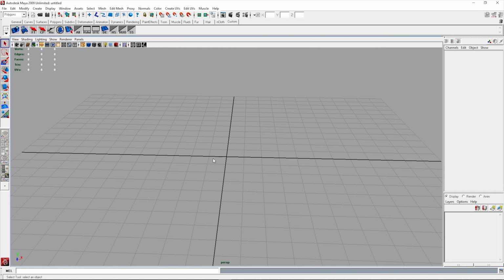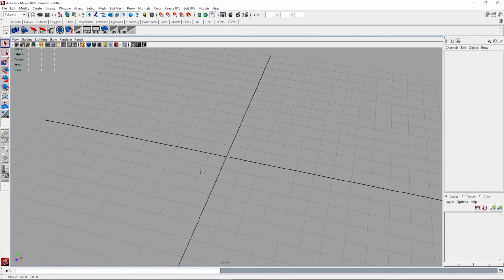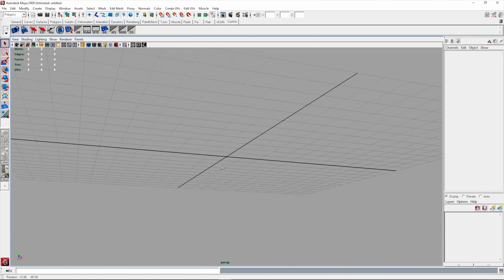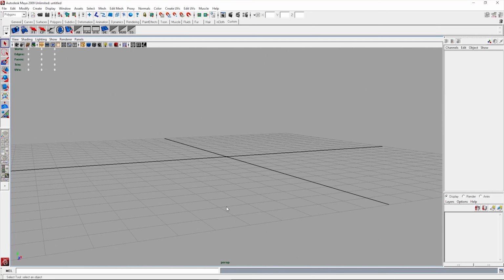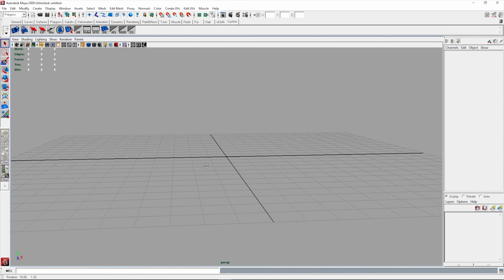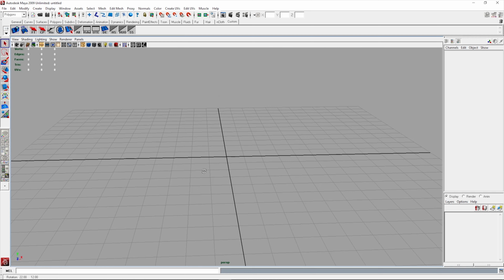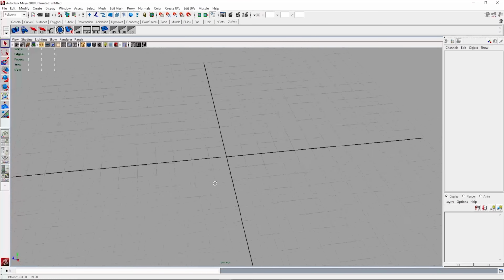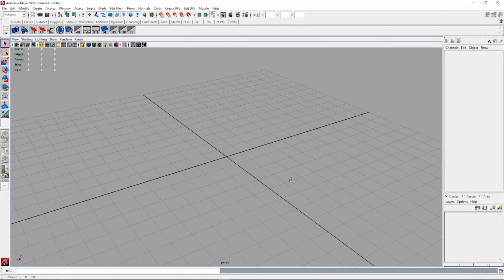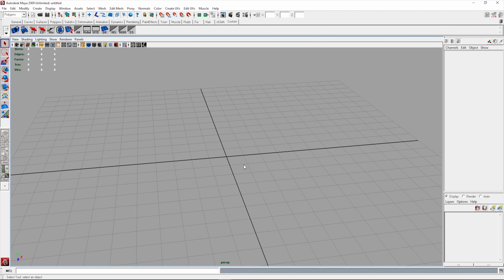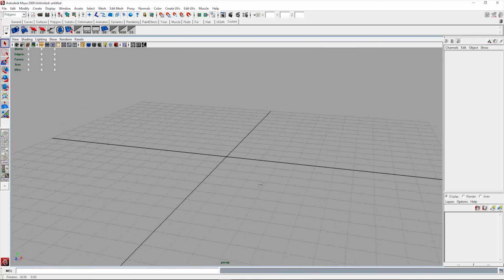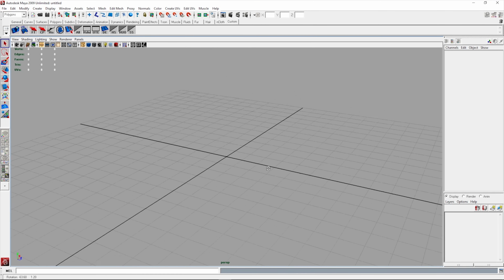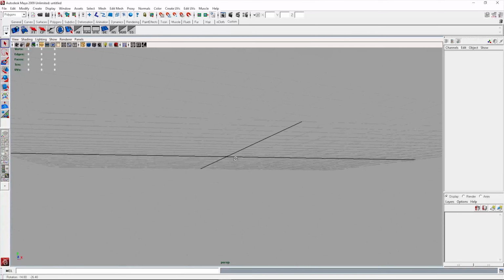Okay, so what I'm doing right now to move around the scene, and I'm focusing on that point of origin, so you can see it's always in the center of the screen as I rotate the screen around. While I'm rotating the world, you're actually looking through the viewport as a virtual camera, and you're moving the camera around that space, which its pivot point is in the center. Now what I'm doing is I'm holding down the Alt key and the left mouse button, and then I just drag around the scene to rotate it.